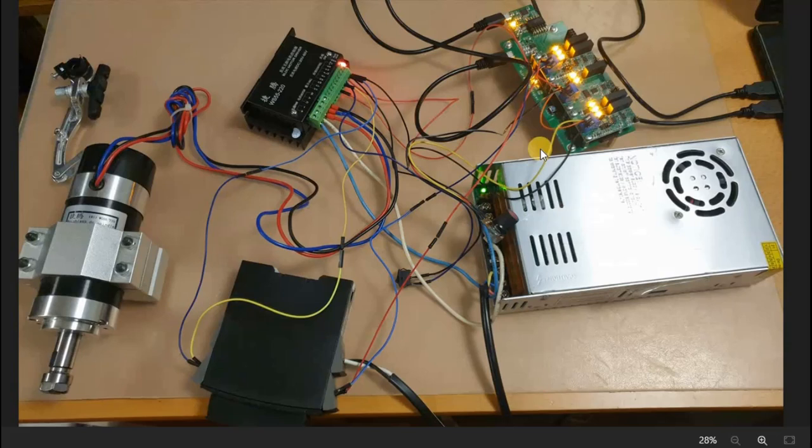Now, for the purposes of this tutorial, we have a demonstration set up in order to show the fuzzy controller development. Here we have the eXdeX hardware, which is of course connected to eXdeX software. Here you can see the PC. We have a power supply here connected to the motor driver. This motor driver, of course, drives this motor. This motor driver takes a 0 to 10 volt signal from an external controller. That 0 to 10 volt signal is going to be generated by this 0 to 10 volt output module on the evaluation board. The motor driver will then generate a feedback signal in frequency.